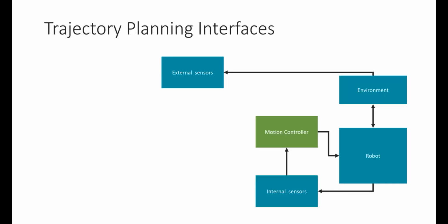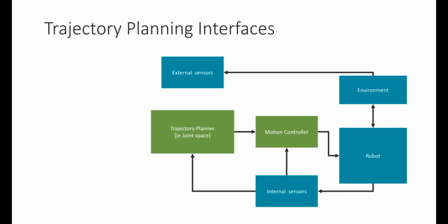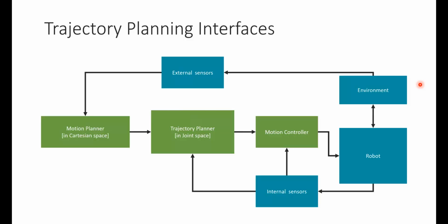So just like these feedback controllers that we're building now, those feedback controllers need a goal position. And that goal position can come from some trajectory planner. And also those temporal dynamics can be fed in from this box over here. And if we have more than one position that we want to get to, then we need some kind of full motion planner to give us all of those waypoints. So even doing something as fundamental to our robot as just moving through space requires a whole bunch of different components, and you have to factor in a whole bunch of factors.